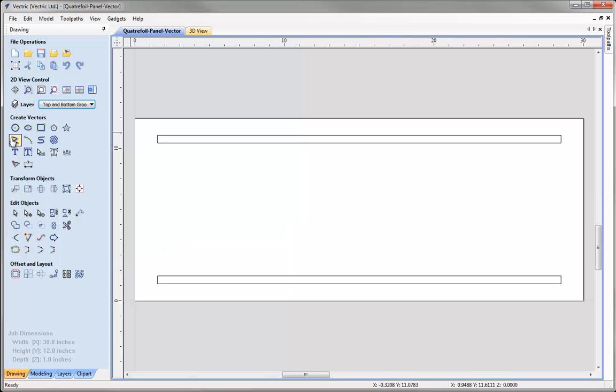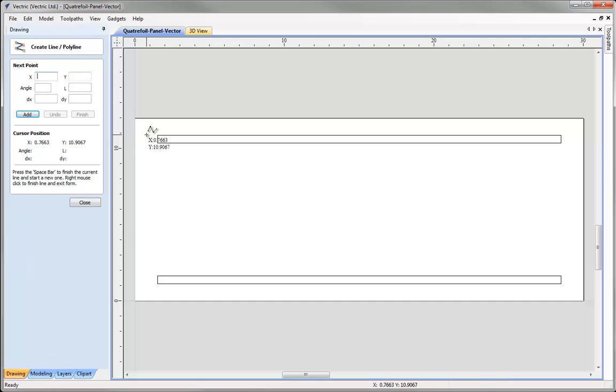And then I'm going to go to the polyline tool, and I'm going to snap to the center point of this side here. So you'll see that as soon as I go near it, it will change the icon to let me know that it's going to snap to the midpoint. So just click once with the left mouse button and then drag it over and wait for it to do that same sign again on this side, like so. And once you've done that, to accept that line, just hit space bar on the keyboard, and that'll accept that line and keep us in the polyline tool.